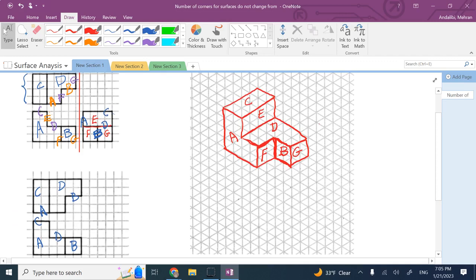Yes. Well, I don't want to redo the analysis, you know it. So that's how we determined A, B, C, and D in the example. Now, the question is, is that enough to draw the right view? Not entirely. Why? Because I did not determine every entity that I see in the top and front. And you might say, what is it that you haven't determined? The answer is the edges. If you look, all of the surfaces are determined, not the edges.